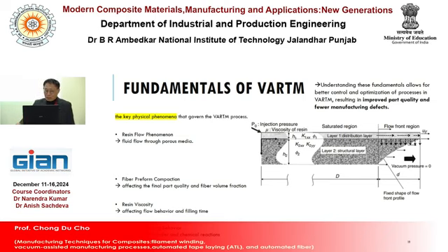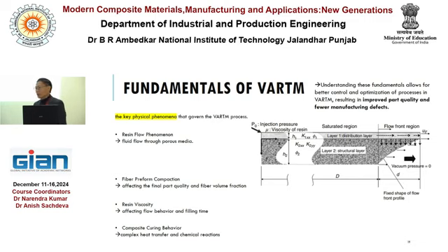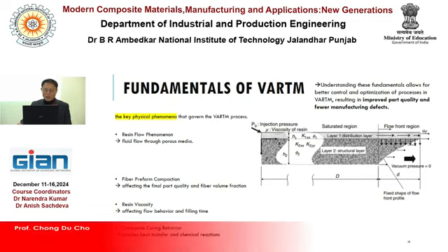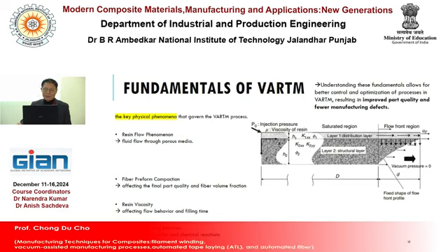So the key physical phenomena for the VARTM process are resin flow phenomena, fiber preform compaction, resin viscosity, and composite curing behavior. These four subjects should be understood to use the VARTM manufacturing technique for your product. Resin flow phenomena is about fluid flow through porous medium.